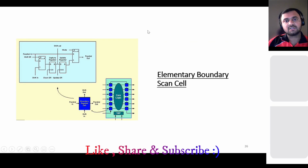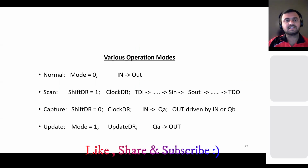Suppose you have 17 instructions, then your bit count becomes 5-bit, because 4 bits support only 0 to 15, I mean till 16 you can count using 0000 to 1111. But if it is 17, then you have to increase your instruction size, and your BC cells will increase. So it is basically decided based on the number of instructions, and this is the basic operation.